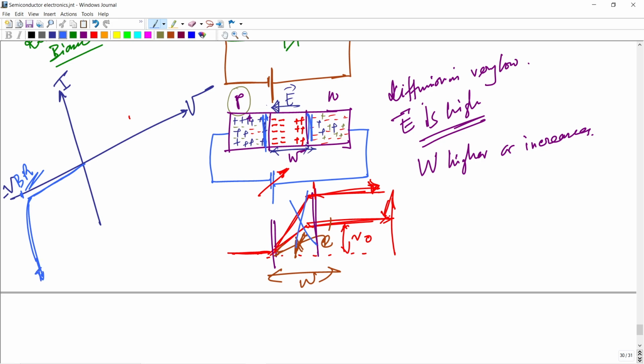If I slightly increase the reverse bias voltage, you get a huge amount of reverse current. Before that, the small current we get is due to minority carriers, which are called drift, due to drift, and these values are very low, and we get this nonlinear graph.